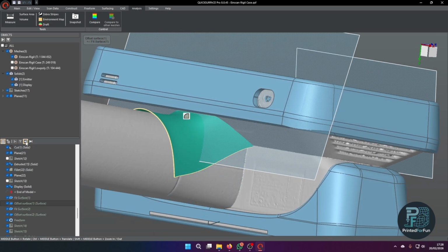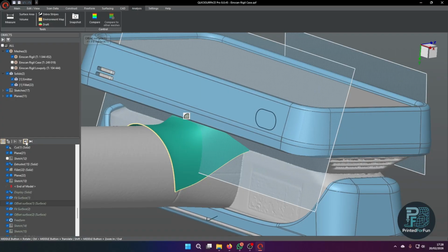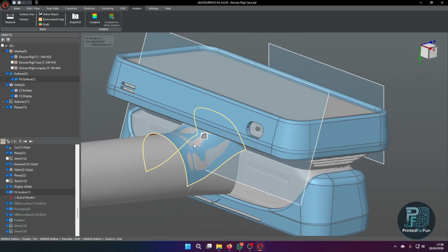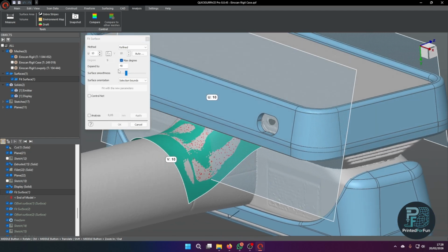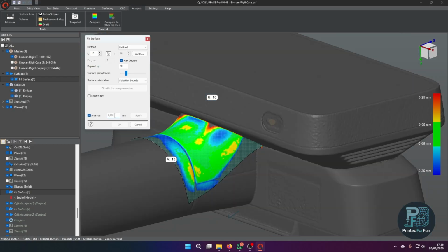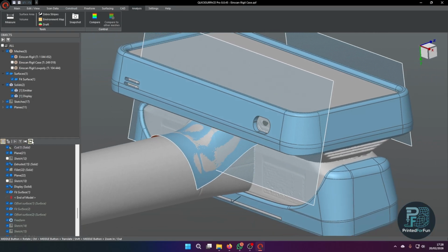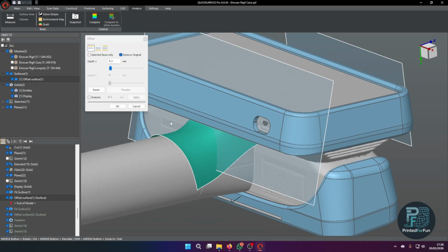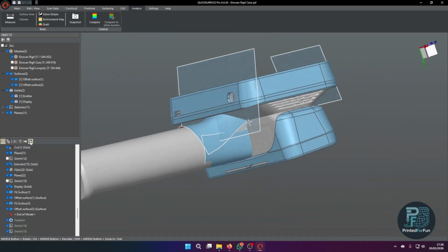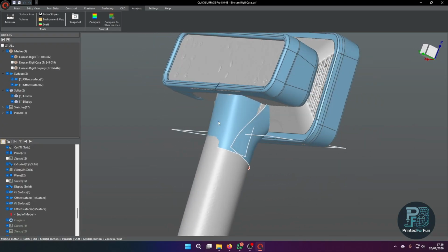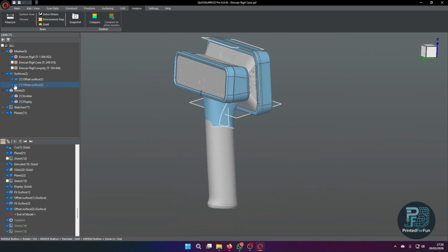As you can see, I'm first starting with automatic surface fitting. I just defined my target tolerance of roughly 0.1 millimeter, and then told the software, go, do your work. I used a slight offset of the surface of 0.2 millimeters to ensure there is enough clearance. I did the same with the lower freeform surface.